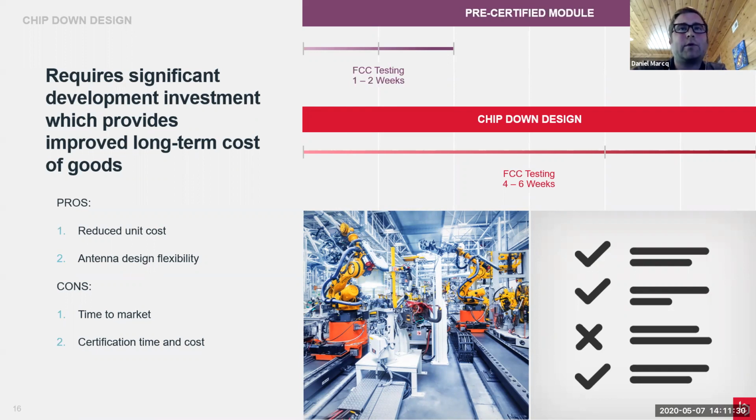Now, I say you can get reduced costs because there is a chance you may overcomplicate your PCBA and actually make it more expensive. Again, that ties back to having an experienced RF designer working on that chip for you. The other benefit is that, long-term from a production standpoint, you have more control over your process, which allows you to pick discrete components. You're not tied to a particular vendor, so there are opportunities to adjust your pipelines down the road to continue to save costs.